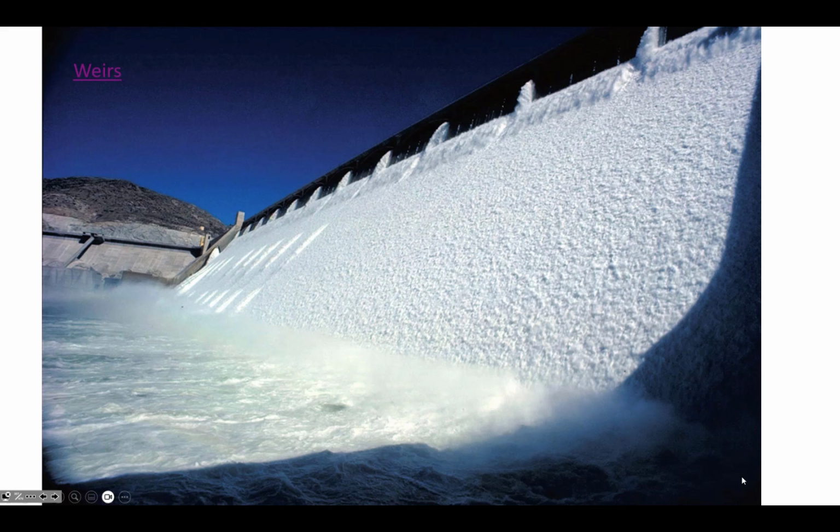So if you are looking down from above, ordinarily the way that these clarifiers would work is that the water is coming in through a pipe, and then it's going out across the top, and then it's flowing outward towards the edge. And so there could be this distance around the edge that's basically the weir length. In the formula, it was telling you that the length of the weir is one of the important parameters that dictates the flow rate out.